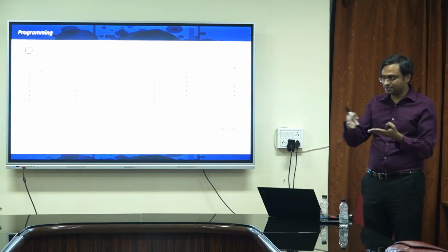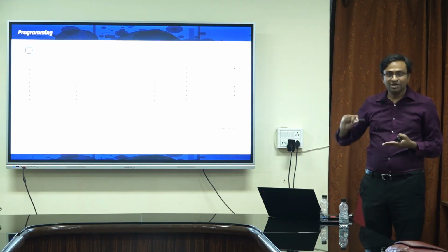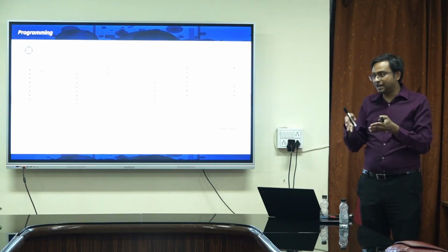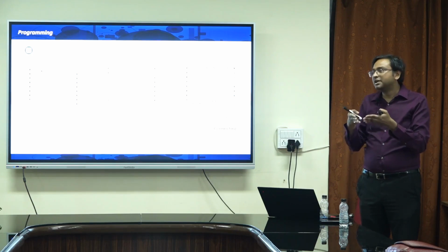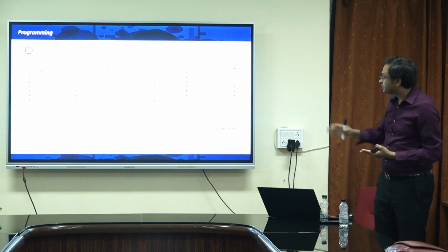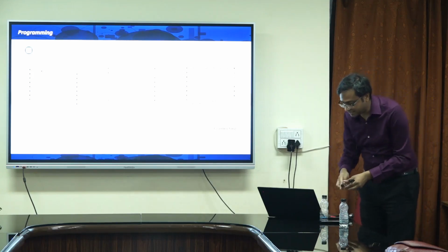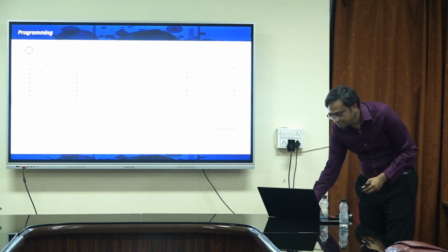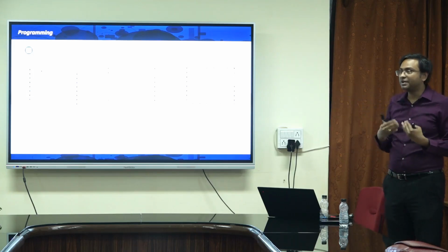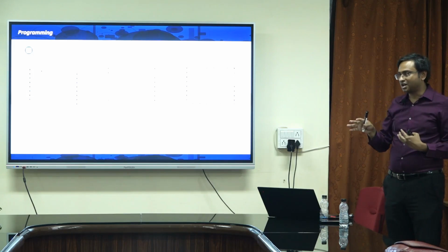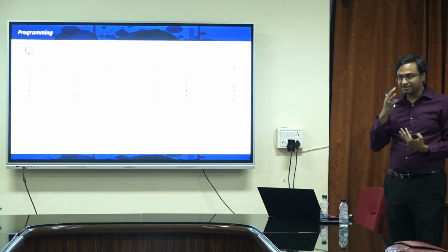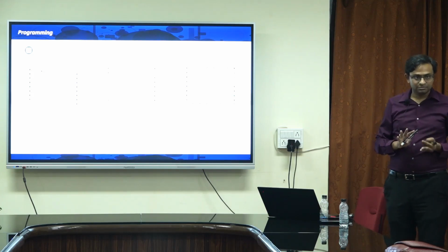Because at the end of the day, the synapses are conducting current between them, and they are actually updating the weight every time you learn something. And when the weight becomes very large, that means you have learned it very well, and it will take a long time to forget it, or it will be remembered forever. Right? So that's the idea of showing this aspect where you have a time-dependent and pulse-dependent response. Pulse is how many times you read, which changes the conductance. Time is how long you read, which also changes the conductance. So this memory device can mimic the brain pretty well. Right? That's the take-home message.